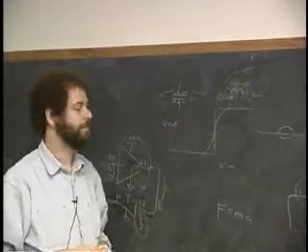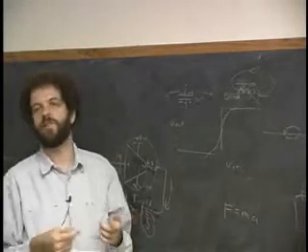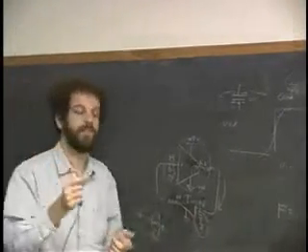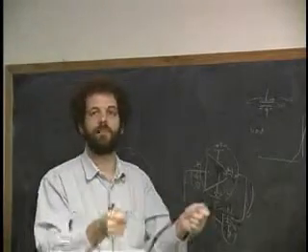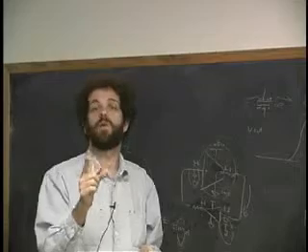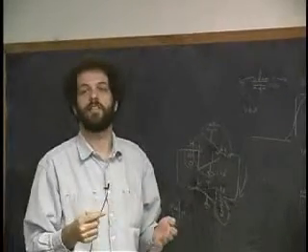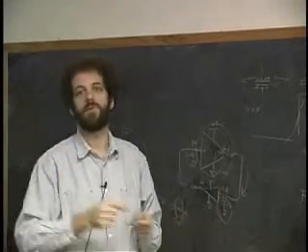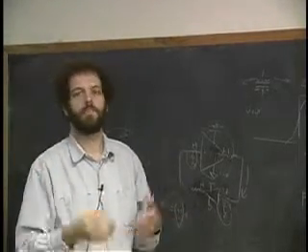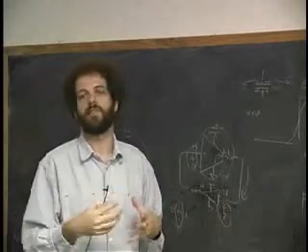And so I don't know how many of you have played with, let's see, the way a spark coil in a car used to work. In the old days, a set of points would short the coil across the battery of the car, and the points would open. And the coil would get so upset about you trying to change the current that you get this incredibly high voltage on that coil, which would cause the spark to happen. And so that's basically working the same way. It's remembering the fact that it used to have current going through it.